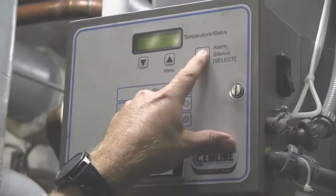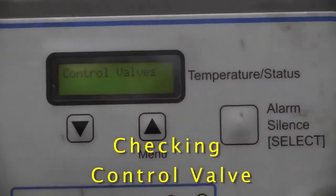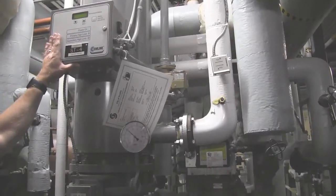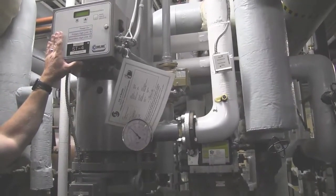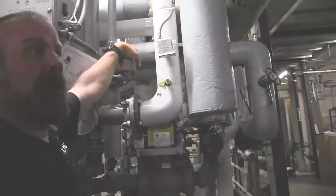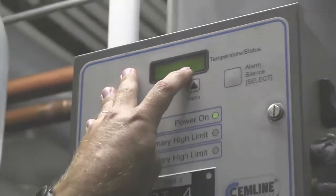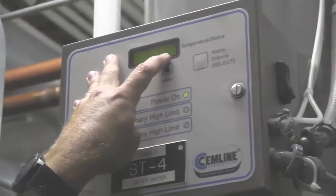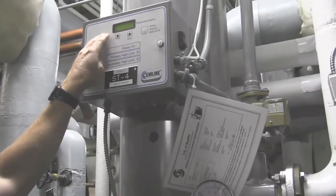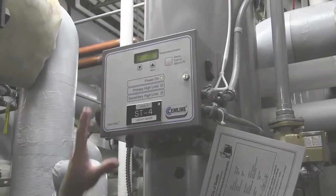So I'm just going to hit the enter button. The control valve setting is set for a single valve, which is what you currently have. The last thing to do is if you wanted to check to see if your sensors were acting properly or your circ pump. With your circ pump, you can typically feel if it's running, but you can also test it. So the 1 volt tells us that it's giving a 1 volt call to open the valve up a little bit to get up to set point of 122. All this is telling you is if you have a single valve, which you do, so we're fine there.